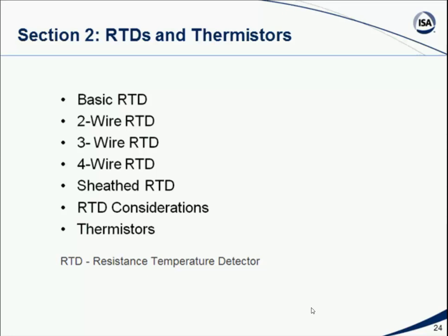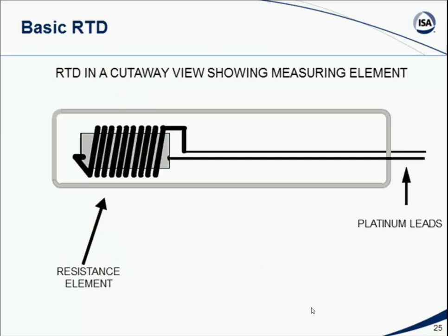To begin with, resistive temperature devices. Essentially, we're just talking about wire, but in this particular case, generally wires based on platinum. So these are not something we just throw around. Wire is a conductor. You can put electricity through it, and all conductors have some amount of resistance. Well, it turns out that some metals, platinum is a good example, change their resistance characteristics as you get them